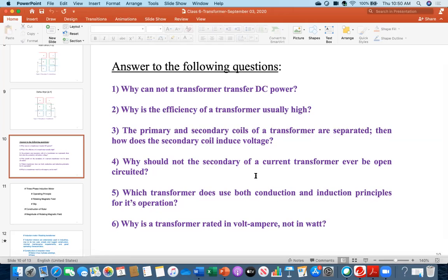It'll be extremely unbalanced and dangerous. Yeah, exactly. Because if the secondary is open, then the energy flow will be unbalanced. That's correct. And it will also be extremely dangerous for the personnel, the technician, lineman, engineer, or whoever is working there. It is a personal safety issue. Because the secondary will have very high voltage, and the core will be saturated because of the excitation current, and again the transformer might be heated up gradually.